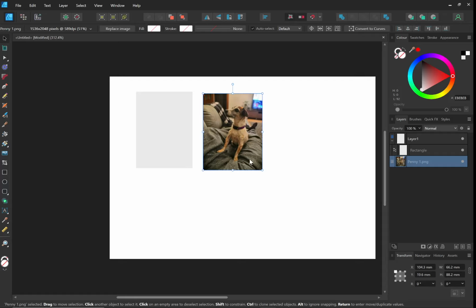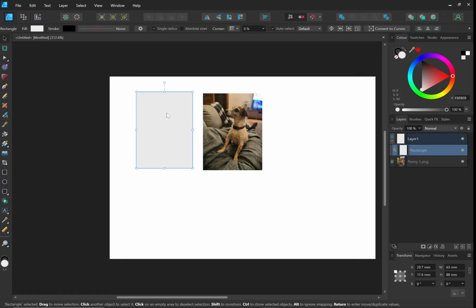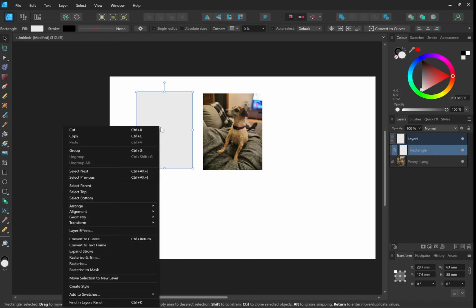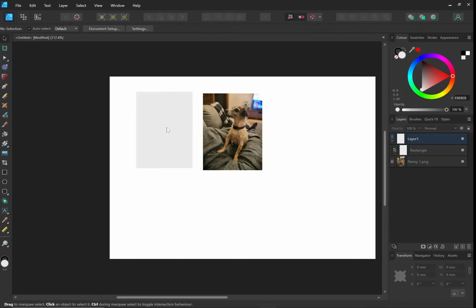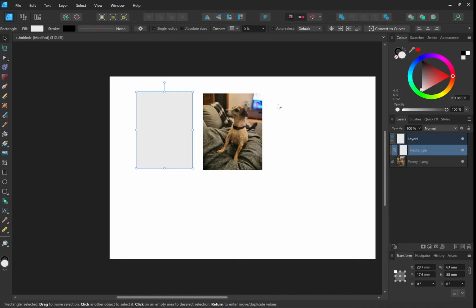Cool. Now I want to make a hole in this particular... How do we do this? How do we make a hole in this rectangle? I have this rectangle here. Then I'm going to use the... So we need to make a border around here for our Pokemon card. We're going to use the contour tool. What the contour tool does is it follows a particular line and makes another line parallel with it. So it's perfect for these borders, right?